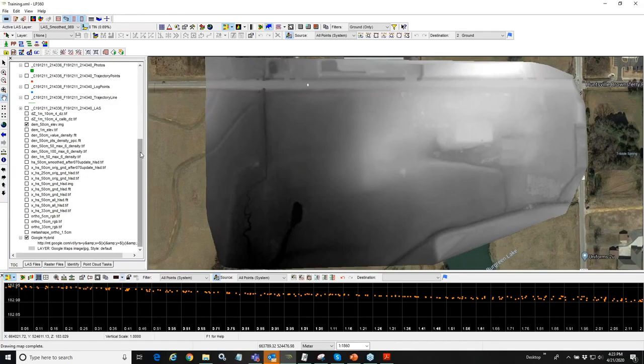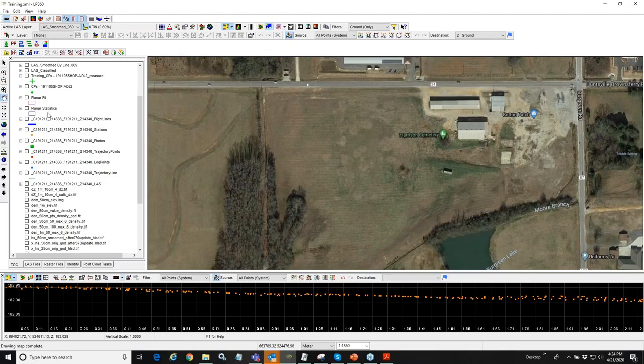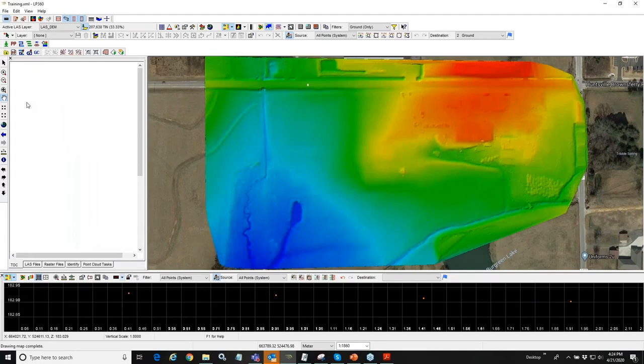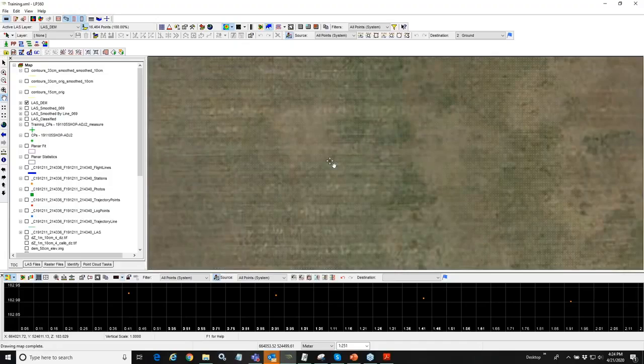What I often like to do, a very standard thing you can do as well, is I can take this DEM and, it seems a little counterintuitive, but I can bring that back in as a point DEM. So I've taken my points, I've rasterized them, and then I've generated a point DEM as well. But the difference is, from a product perspective, those points are now on a regularized grid. That is, I've got an elevation point every 50 centimeters apart.